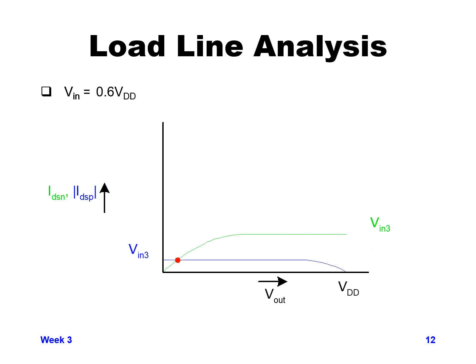Now when we get from 40% to 60% of VDD, our blue and green curves kind of flip each other. Now the green curve has more current than the blue curve, and where they intersect is now way down close to 0, close to ground. And so our output voltage in this case, when Vn is 0.6 times VDD, or Vn3, is probably 10% of VDD or lower. It's getting pretty close to ground.